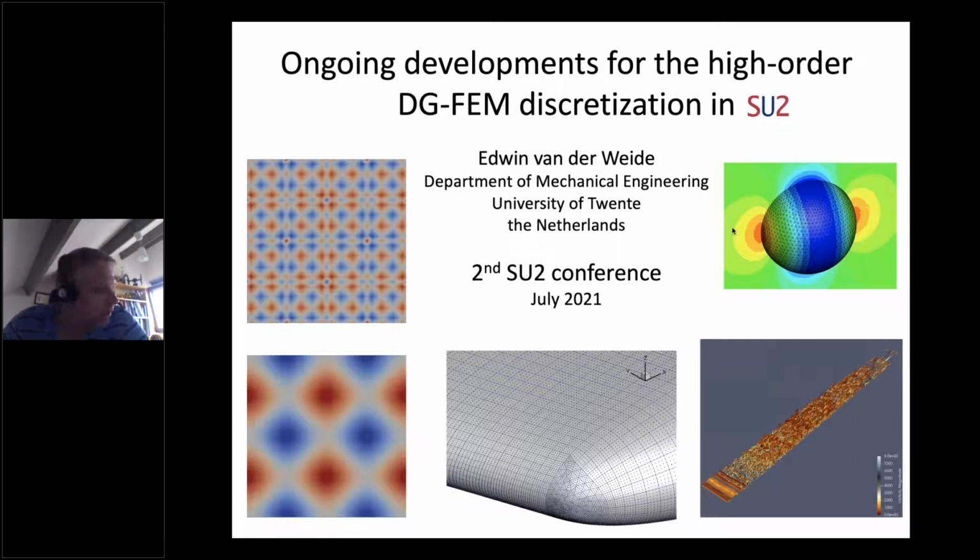I would like in this presentation to give an overview of the work that we have been doing and are doing on the high order discontinuous Galerkin finite element discretization in SU2. You heard a talk yesterday also about high order schemes. That was on WENO schemes. That's a different way of getting high order accuracy, but we are here focusing on the discontinuous Galerkin approach.